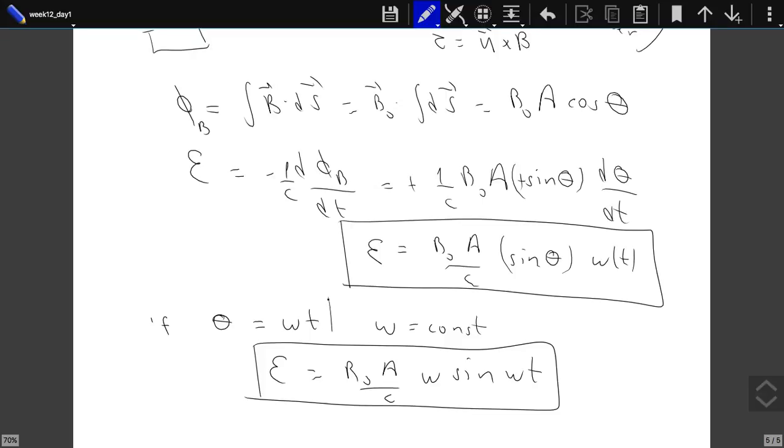Well, you see, now what is theta? And phase difference between what? If you want to have a phase difference, you have to tell me at least two things which might differ in phase. So here we are only talking about the EMF. If you use this EMF to run a circuit, then depending on your circuit, there might be a phase difference between the EMF and the current running in the circuit. But since there is nothing to compare it with, it doesn't make sense to talk about phase difference.